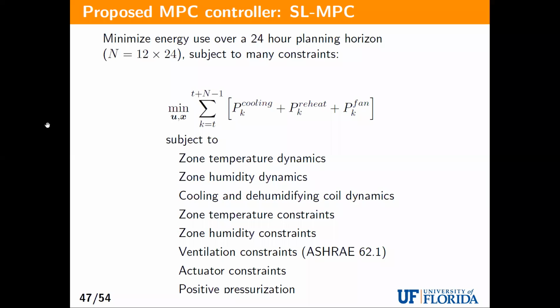So over your planning horizon you're optimizing over 288 times 4 control commands, because at any given time you have to choose these 4 variables: flow rate, 2 temperatures, and a return air ratio. And then there are 288 of them over the 24 hours. The problem dimension is actually much bigger because of the dynamics, which introduce all the extra state variables. So this is the first problem we solved.